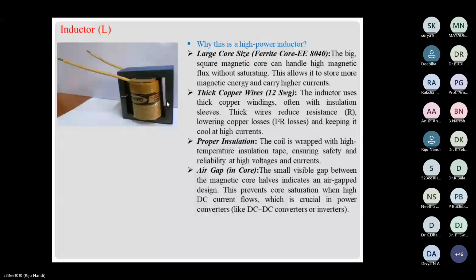Another aspect: if the gap is increased, we say there is some leakage flux. Please correct me. Leakage is there, but the inductor value also increases, and it won't affect much. With a little gap, not more than 2, 3 or 4 sheets of thin paper, you have to put something.